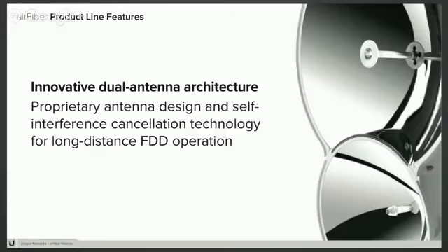Finally, this antenna supports something which is a little unusual. That's slant polarization. We're a two-chain MIMO radio. However, rather than doing vertical and horizontal polarization, which is pretty typical out there, we're using slant polarization. And the reason for that is that it helps us better isolate reflected signals. As a result, it takes advantage of the fact that a lot of the reflective surfaces that you'll see out there are either horizontal, like the ground, or vertical, like a building. But when you put this all together, what it adds up to is excellent full duplex performance.